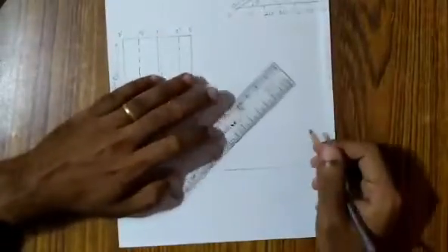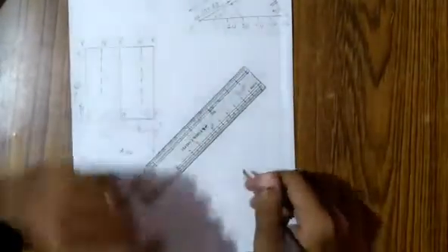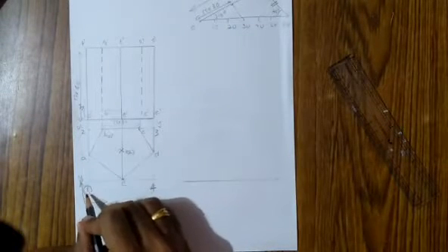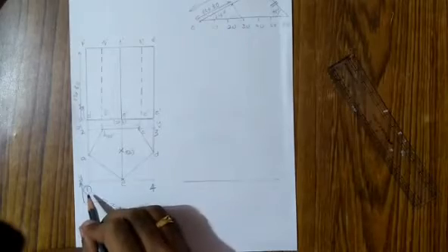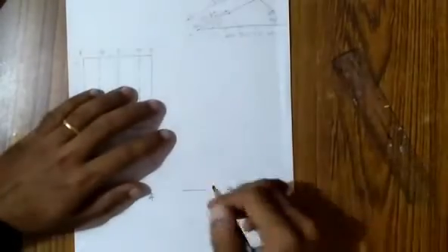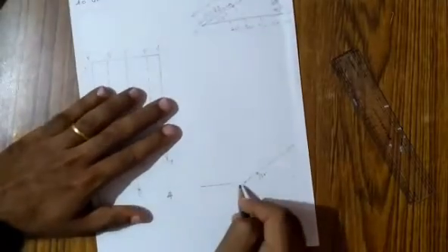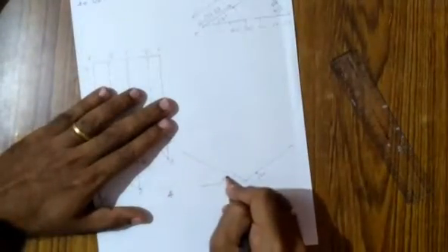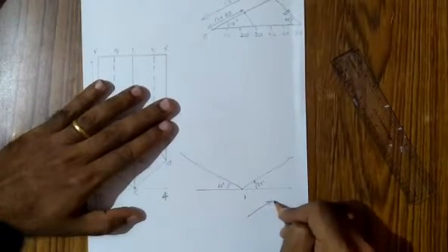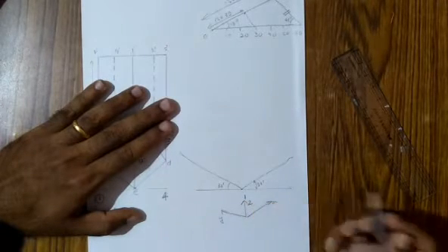Okay, we have drawn the base, and as you know, the X and Y is going to be at an angle of 30 degrees. So let's take the left corner bottom point as your reference. So I am taking 1 as my reference, the salient point 1, and I am drawing a 30-degree line. So one 30-degree line to the right and the other 30-degree line to the left. So this 30 degrees has to be shown, which is very important. So this is going to be your X direction, this is going to be your Y direction, and this vertically upward will be your Z direction.